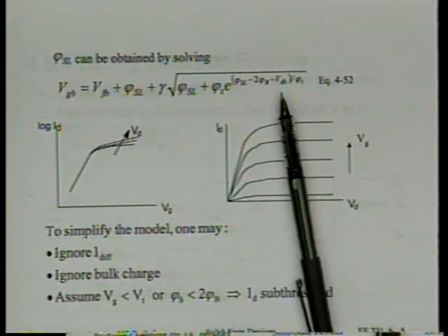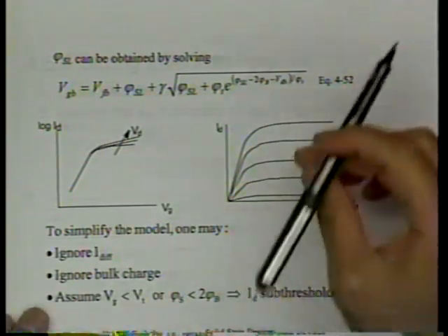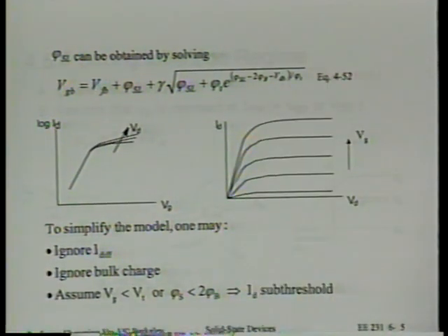Now you see in a transistor we actually don't just have 2 Fermi levels, we have 3 Fermi levels. What are these 3 Fermi levels? One is the body, called the VFP, we talked about earlier. One is what we call the VSN, which is the Fermi level from the source side. Now the drain side gives us a 3rd Fermi level. Can you visualize that? Because the drain to body p-n junction is reverse biased at a different value than the source to body. Is that right? So now we have 3 Fermi levels.